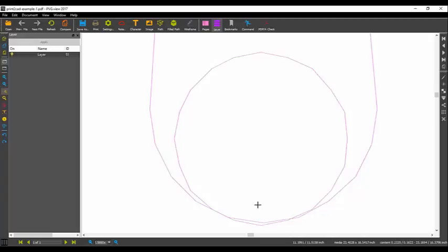What is a DPI raster? DPI raster is a coordinate raster you use in your plot. Or if you print it as a raster picture, for example on your plotter, this DPI is a resolution of the picture, and the normal resolution of a print is 300 DPI.